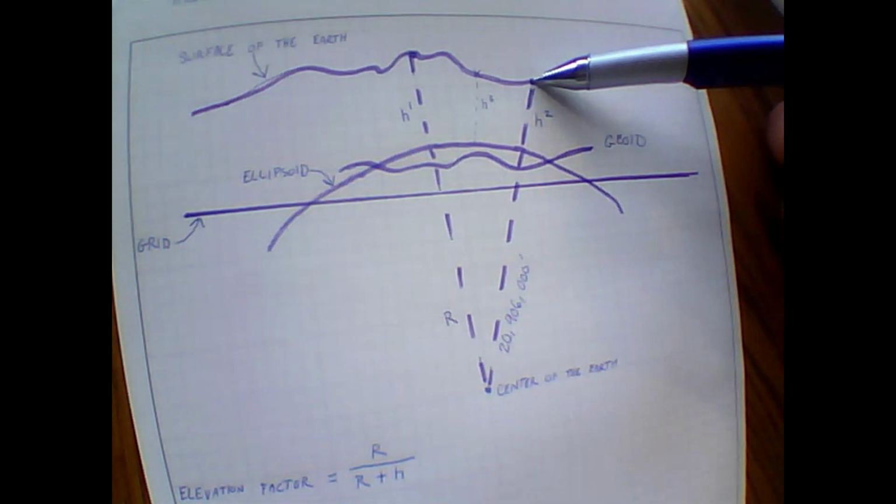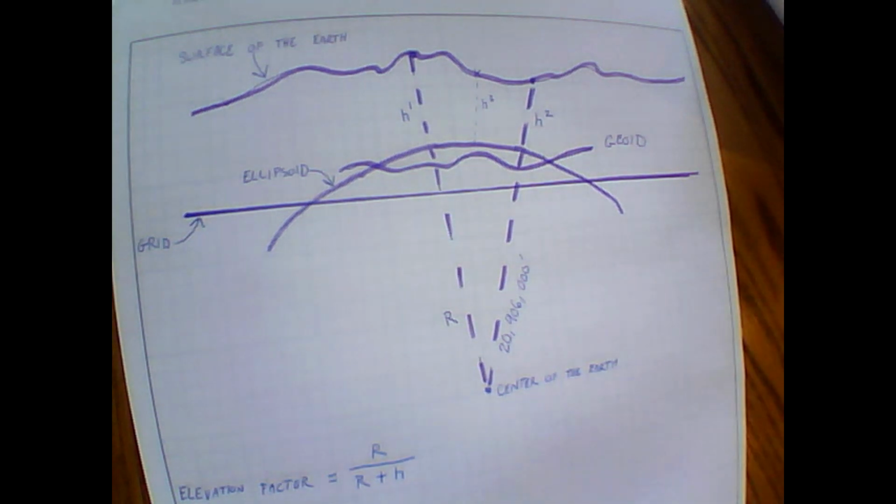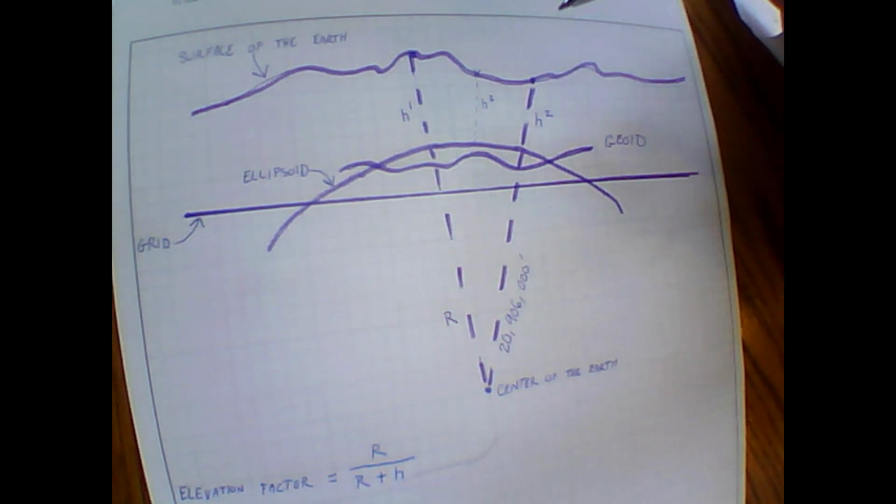middle, longest. So the reason this is done is because this is for larger projects, really big projects, to take the curvature of the Earth out of your coordinate system and just remove it. That way, you don't have to deal with the curvature, and everything you measure is going to be relative to each other. There's not going to be much distortion. There's always going to be distortion, but this will relieve a ton of it so that you can work on that state plane grid.